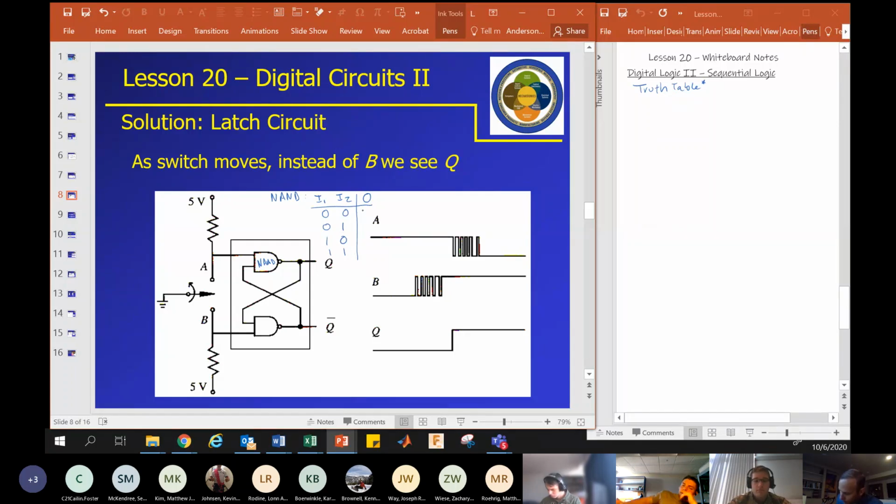So here, if it were an AND gate, we would only get a high value right here, but it's NAND, so we flip it. So the only low value is when both inputs are high, and all the other outputs are high.